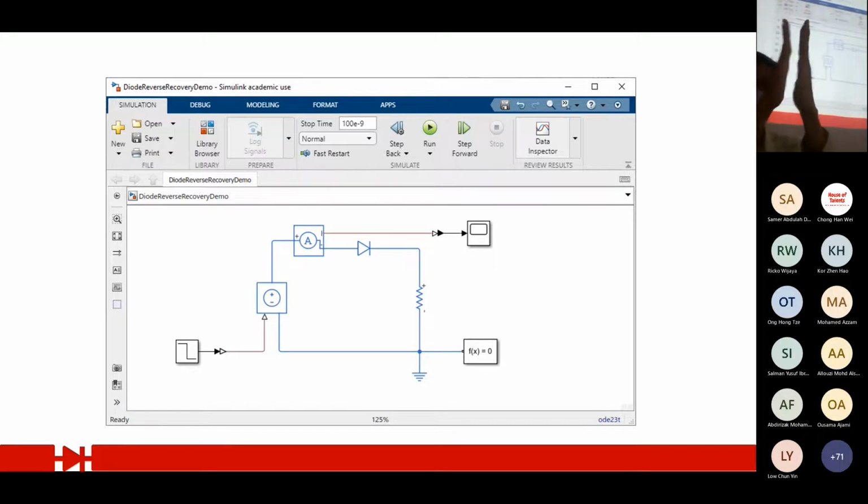It opens, there are still electrons combining with the holes. So that means during this very small fraction of time, in microsecond, it is already reversed, but it still conducts current in both directions. So this phenomenon is called reverse recovery, because in reverse, it slowly recovers. All right. Now, you can only see this thing again in the semiconductor factory when they test your diode.